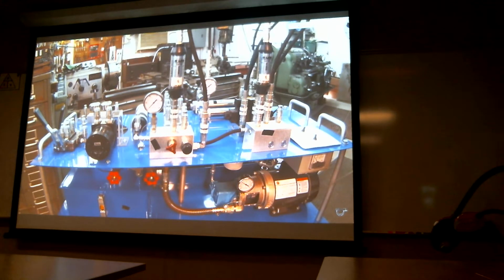If it's the electric motor, it'll kick the electric motor out. If it's a hose, it'll rupture the hose. I've seen actual bodies of your pump housing blow up. So if you don't have a safety relief valve in a hydraulic system and you get a clog somewhere, the pressure will go as high as it wants to, okay, until it finds the weakest link.